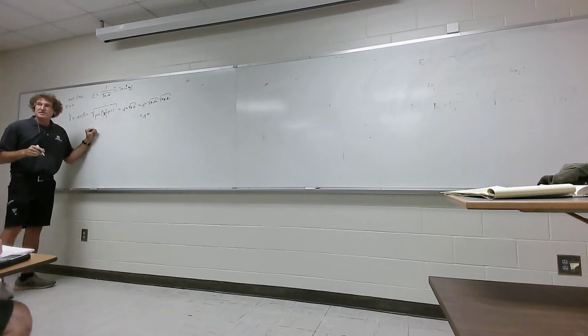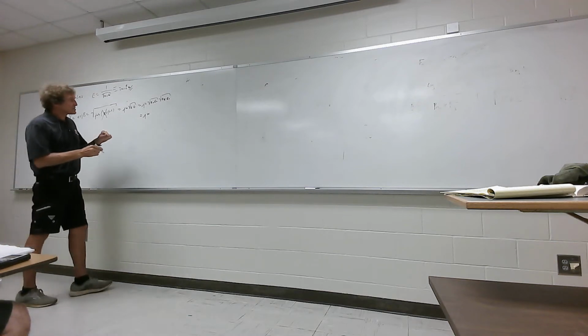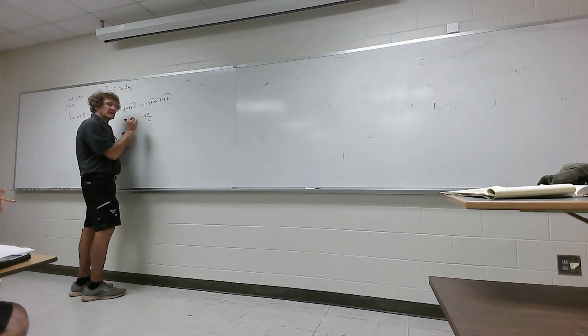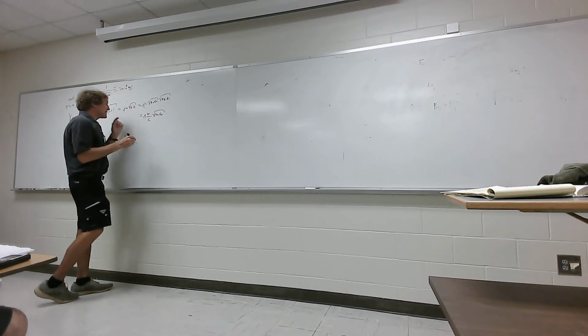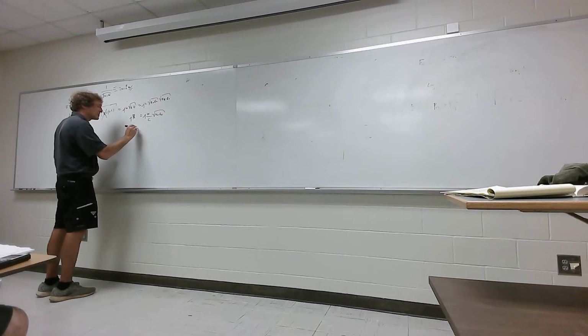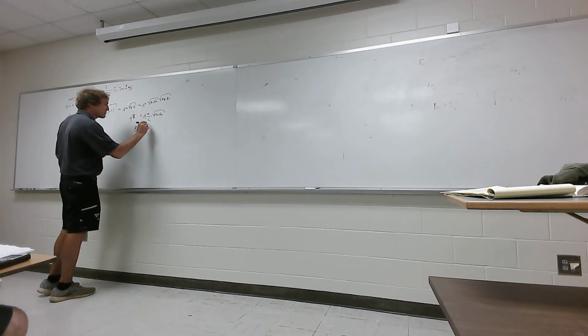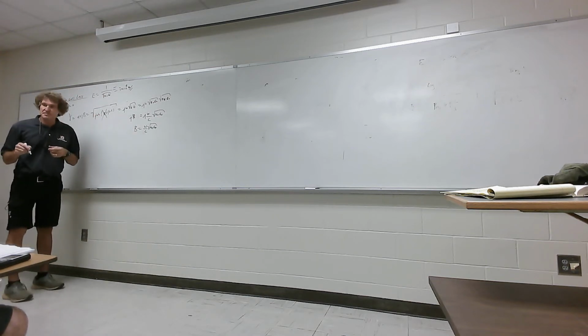If you're an electrical engineer, electrical and computer engineer, that's something that's got to be known without question. You come down here, so that's really omega over c, times the square root of mu relative epsilon relative. And that is simply going to be just j beta. Alpha is going to be 0, and that means beta is simply equal to omega over c times the square root of mu relative epsilon relative. And that's for a lossless material, or a lossless region of space.